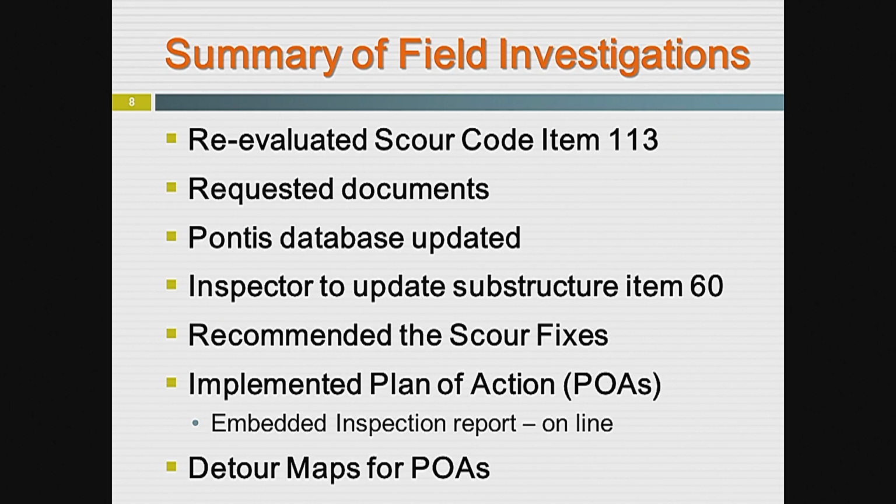And then once we finished with the scour field trip, I updated it in Pontis, so the inspector who went out after me could code it correctly in the inspection, and then we definitely talked about how the scour code should be fixed or whether it's stable, and then we talked about the scour plan of action.